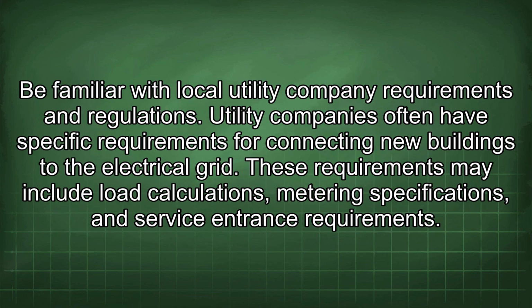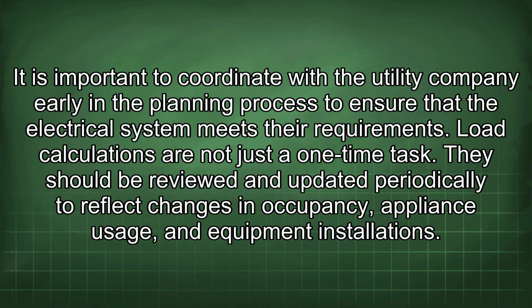Be familiar with local utility company requirements and regulations. Utility companies often have specific requirements for connecting new buildings to the electrical grid. These requirements may include load calculations, metering specifications, and service entrance requirements. It is important to coordinate with the utility company early in the planning process to ensure that the electrical system